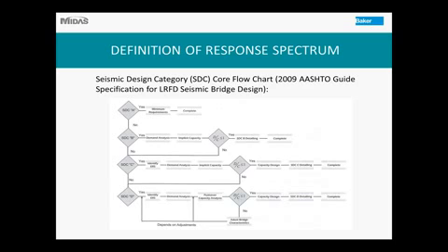And then SDC C and SDC D, they require you to identify your lateral load path. What is your load path to resist the seismic loads? And you need to do a demand analysis, and you also need to do pushover analysis to come up with your displacement capacity. Of course, you also need to do the detailings.